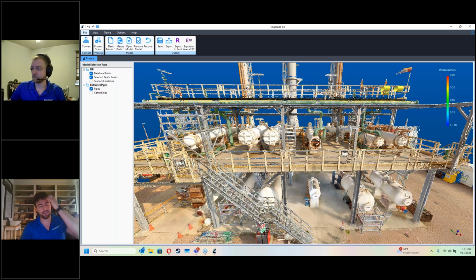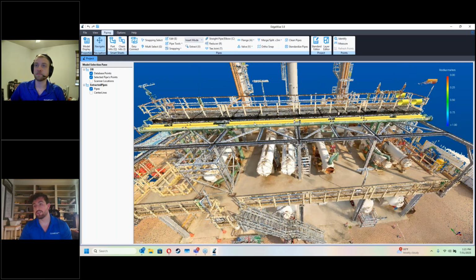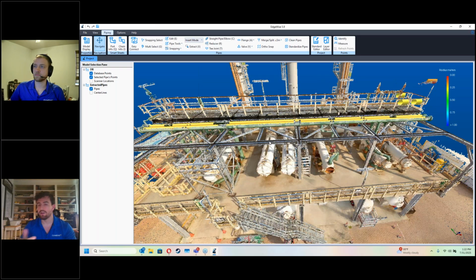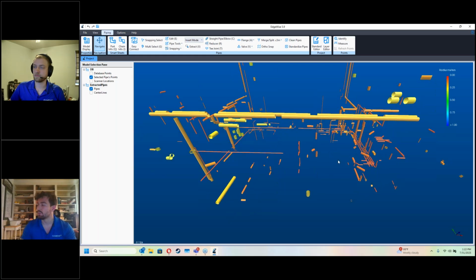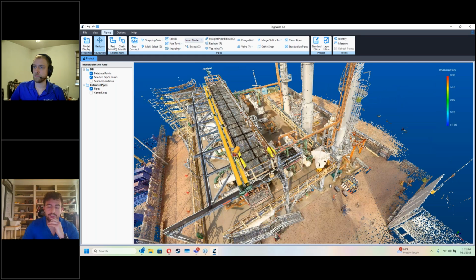Yeah, it's loaded. Perfect. So a new feature, or something I more want to just state, because I see one of the questions is SLAM data. EdgeWise currently does support unstructured point clouds. The main thing is the fuzziness. If SLAM data is clean and filtered, then we can run the automated routines on that for piping and extract out some pipes. In this case, I actually have Navis data. So we can run through using this Navis data set, for example, and you can see it connect and automatically extract out piping. This is what we'll use to demonstrate the new features. All right, speaking of that, let's actually do some modeling.